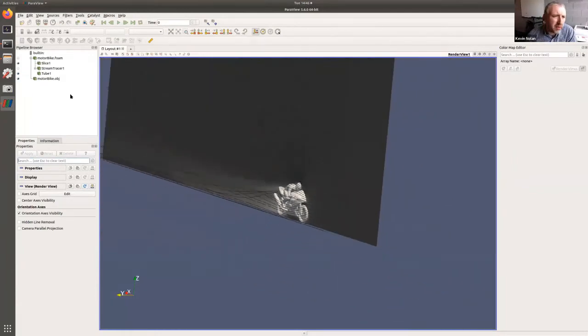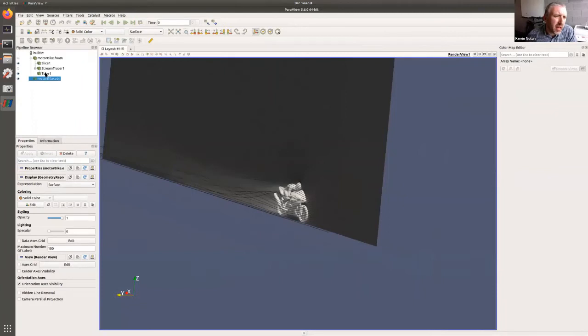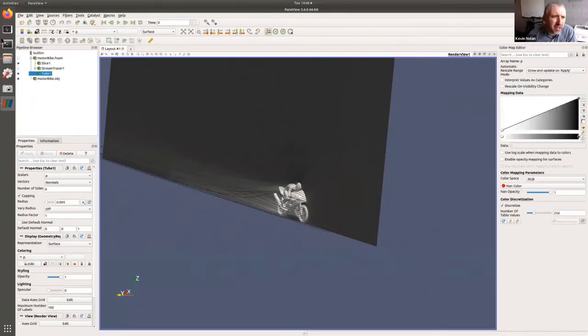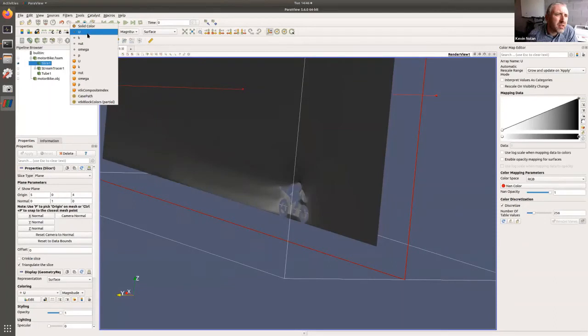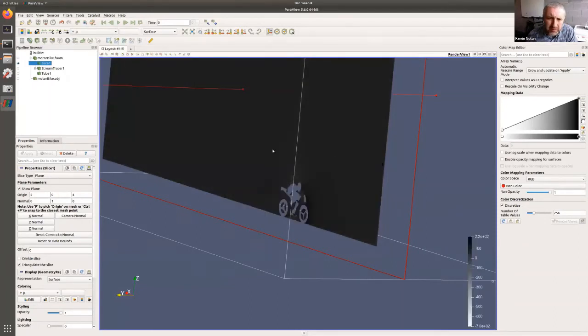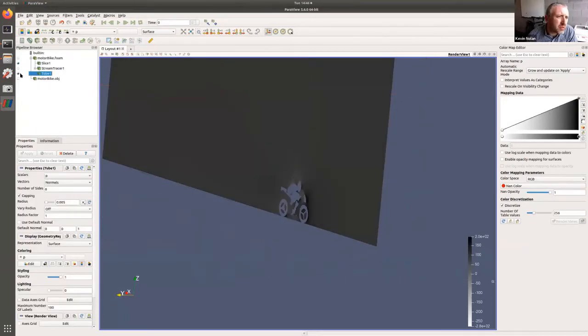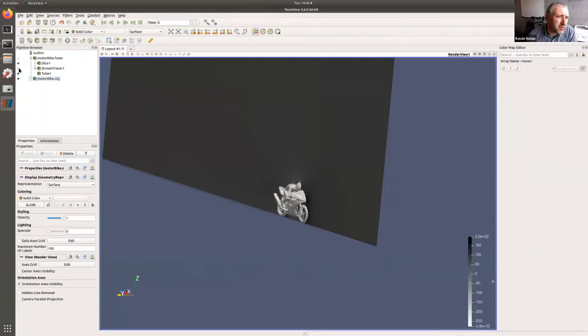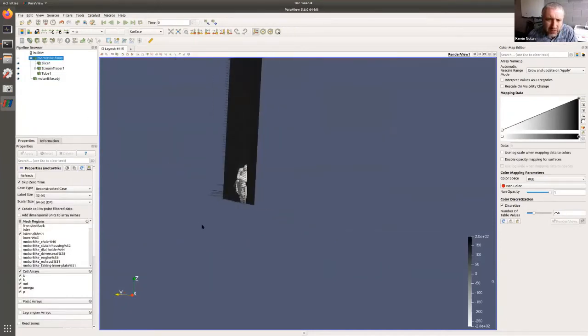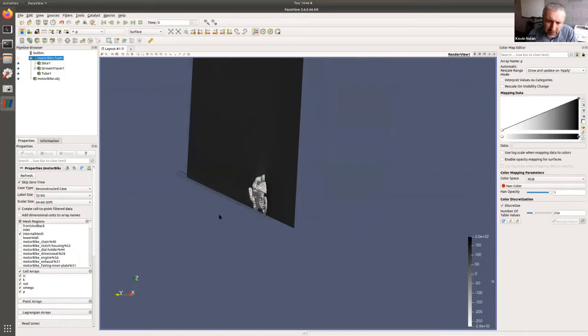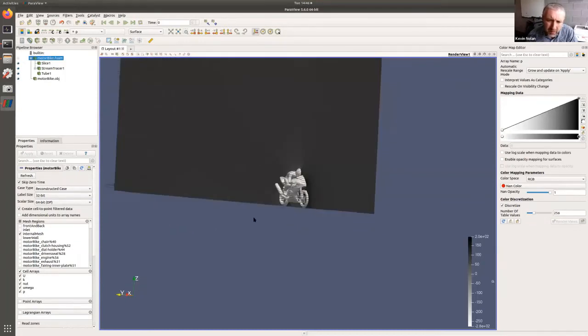This is just, I have the OBJ file of the motorbike. I have stream tube plot showing velocity and a slice here showing pressure. Okay, so it's a pressure slice, there it is, okay? And you can make these guys whatever you want to make them. So stream tube, motorbike, and so forth, okay? So here's our geometry we're going to work with. Now I've turned off the main volume because this is just too much information, but there we go.